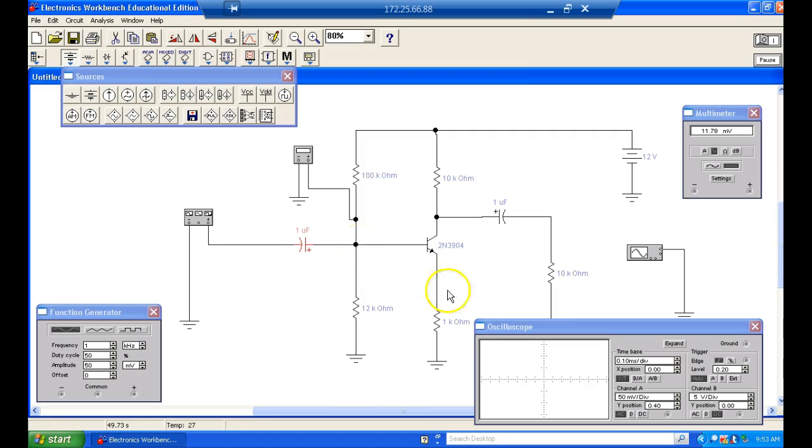What happened though is when we came over here and opened this resistor right here, it caused the base voltage to go down a lot because we lost beta, right? Remember that? So when this guy's real low, of course, we still have millivolts, right? You understand that. A while ago, when we opened this resistor right here, it went to microvolts, right? You understand that. So it could either be this guy or it could be that guy.